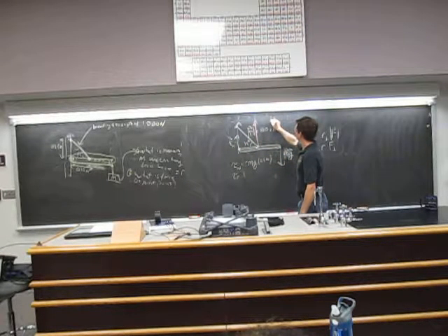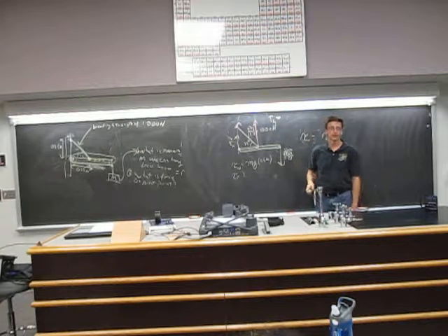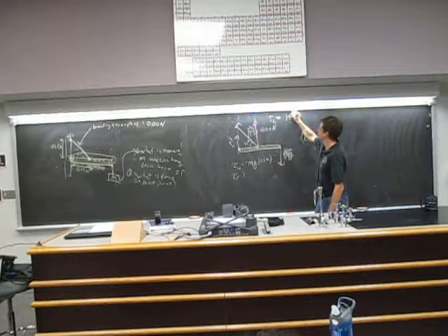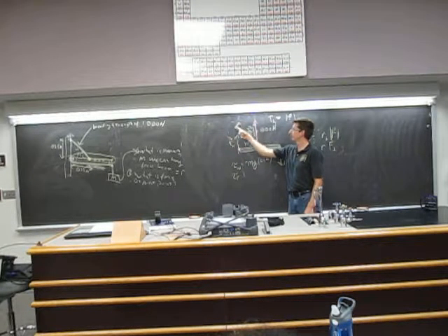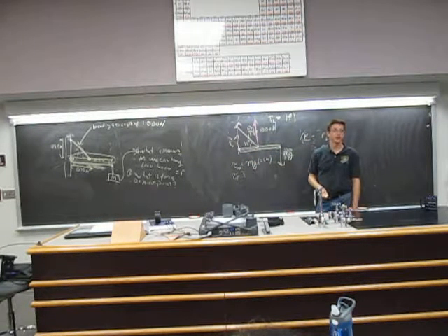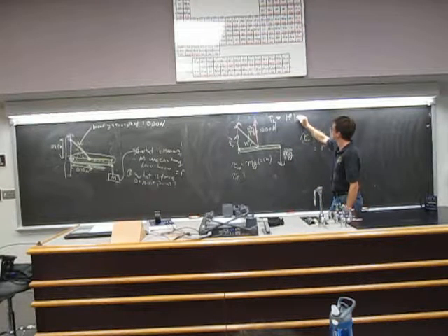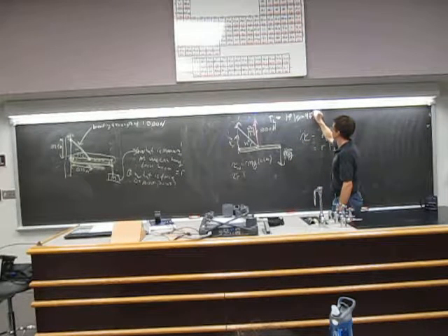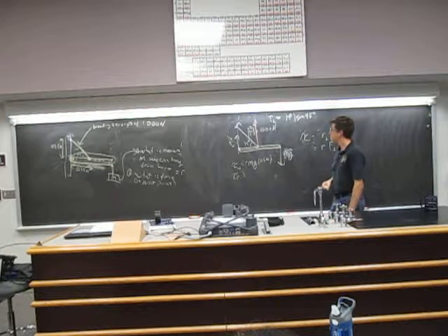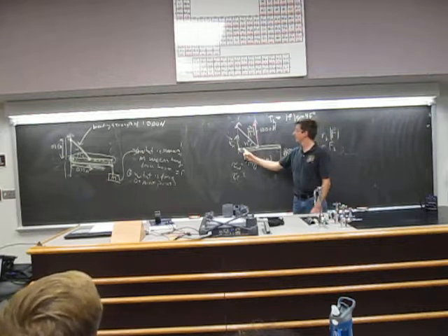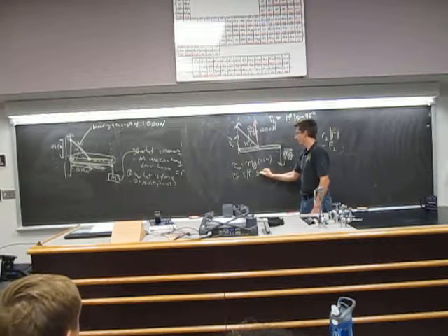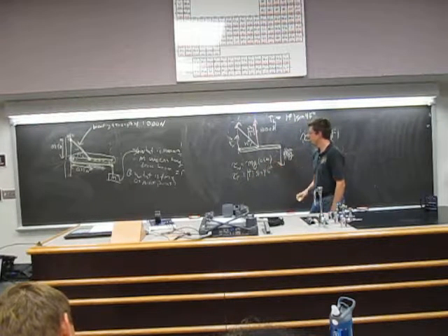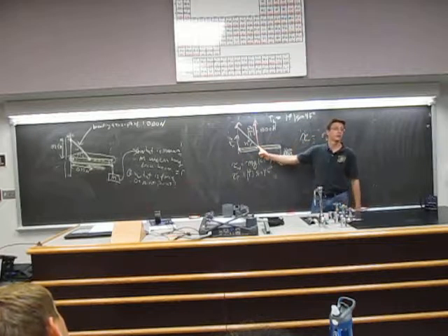So tension perpendicular is going to be the magnitude of the tension force times, and this is the opposite side of this triangle, the sine of 45 degrees. And then this distance is a quarter meter, so I could do tension, sine of 45 degrees, times this quarter meter here.